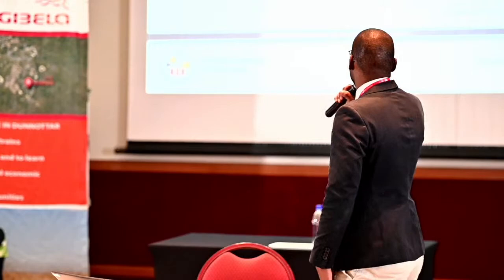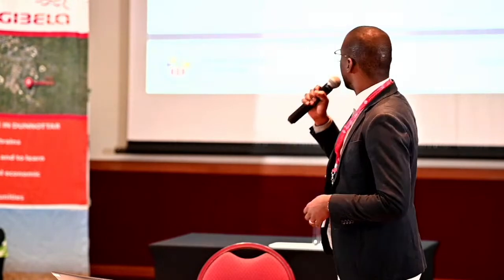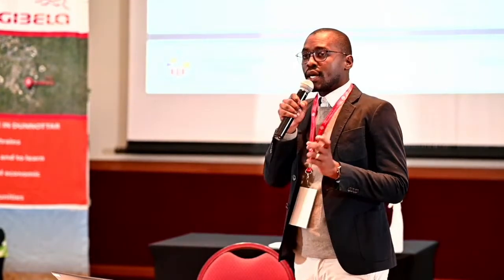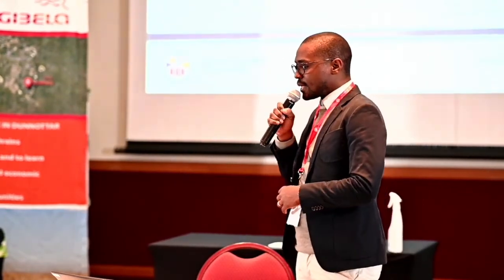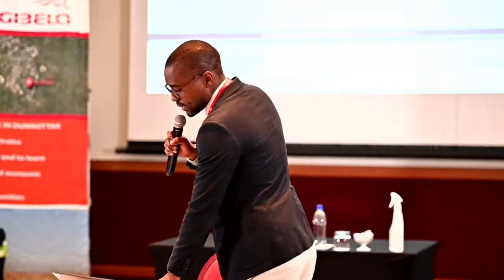Coming to the results, with all the inputs, inputting the different faults in the tool, it will calculate the SAIDI and SAIFI performance. As you can see with this one, the target was 2. The municipality aims to achieve at least 2, which is also a NERSA regulation. From the graph, it's seen that the performance is out. I was also able to identify the different feeder performances, and from this we can see which feeder needs urgent maintenance and improvement.